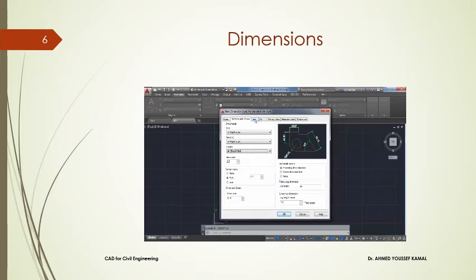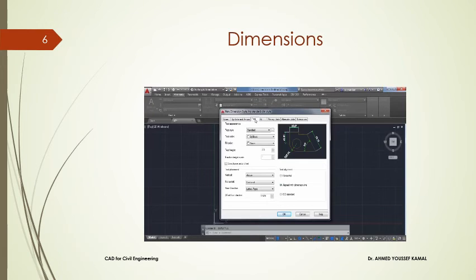When you move on to this text tab, you'll also see that we have a text height which is generally equal to the size of our arrow. So here also you can change the size of text. For example, let's change it to 5 units and press tab. Now the size of this text changes to double its original size. Let's keep it at 2.5.